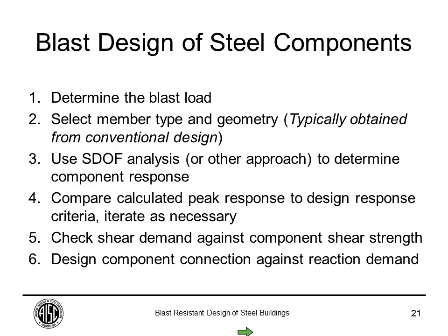So let's just talk about that step 2. We're assuming that we already have a hardened envelope around our building. So let's just look at the steps when you're starting to design the blast steel components. At the very beginning, when we showed the video, we talked about the simplification of the blast-resistant design. You have this massive amount of energy that loads your building, and it pushes us in all different directions and causes compression, twisting. So we look at that and we simplify it, and we look at it on a component by component basis.